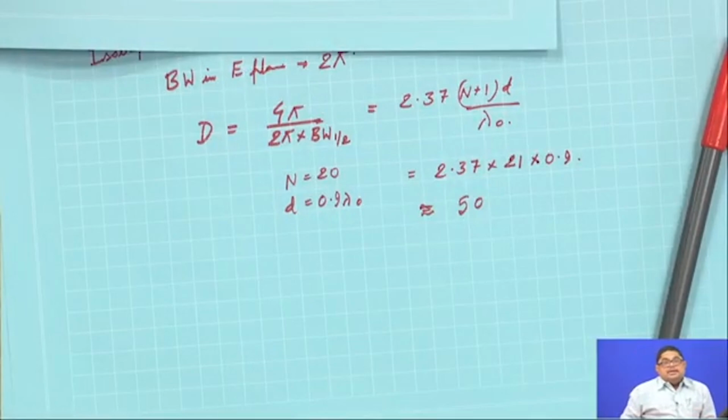So, not bad. That is why in array antenna the main contribution comes from the array factor. So, you can put any antenna. Obviously a dipole will be preferred over isotropic radiator in the sense that you will have the power handling capability and other things. So, any type of practical antennas will do.